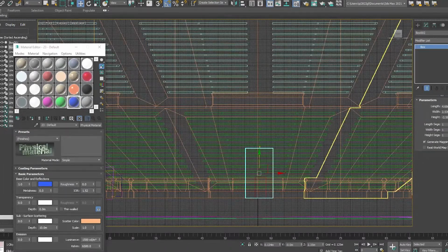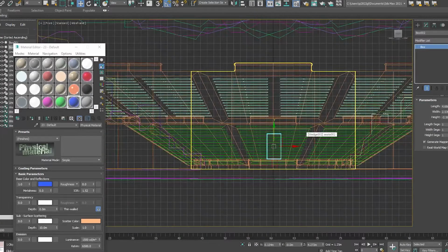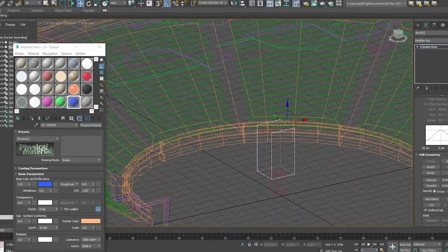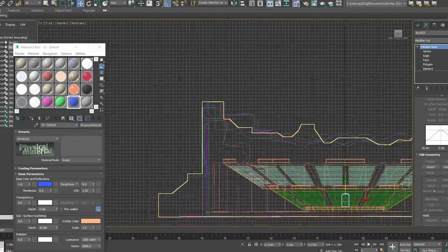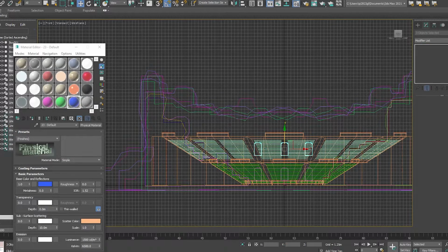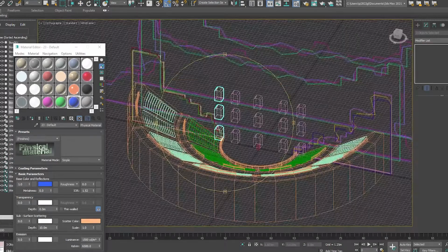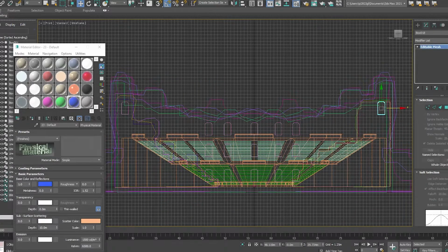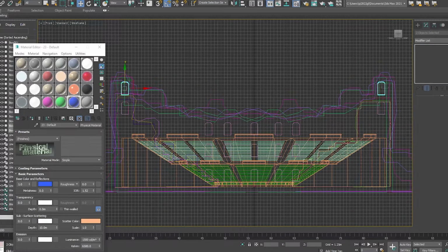And now I'm creating cutouts for the Boolean subtraction that I'm going to do. All of these walls have a variety of doors and windows and little holes cut in them. And I'm going to achieve that effect by, once again, just starting off with a line. Although I think this was a box and I chamfered two of the edges. But you can do it with a line too. Still very low polygon count. And I'm copying this around.